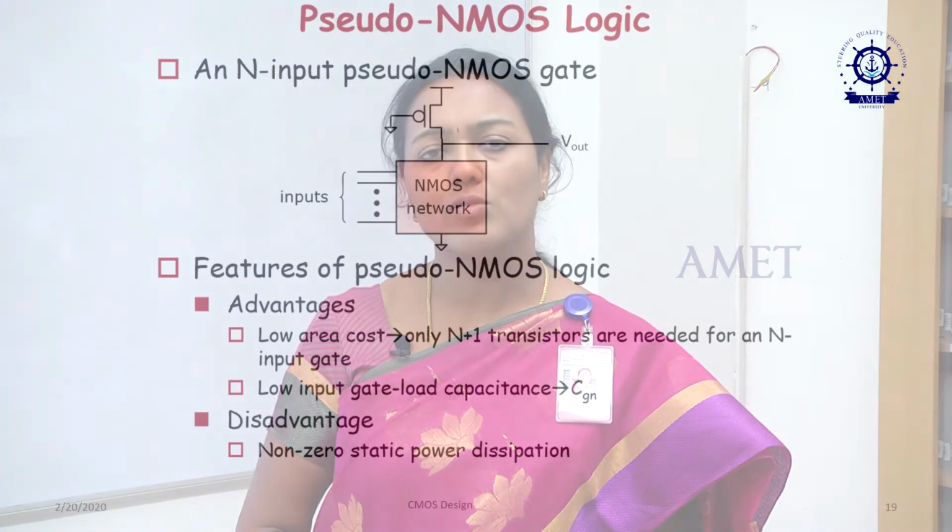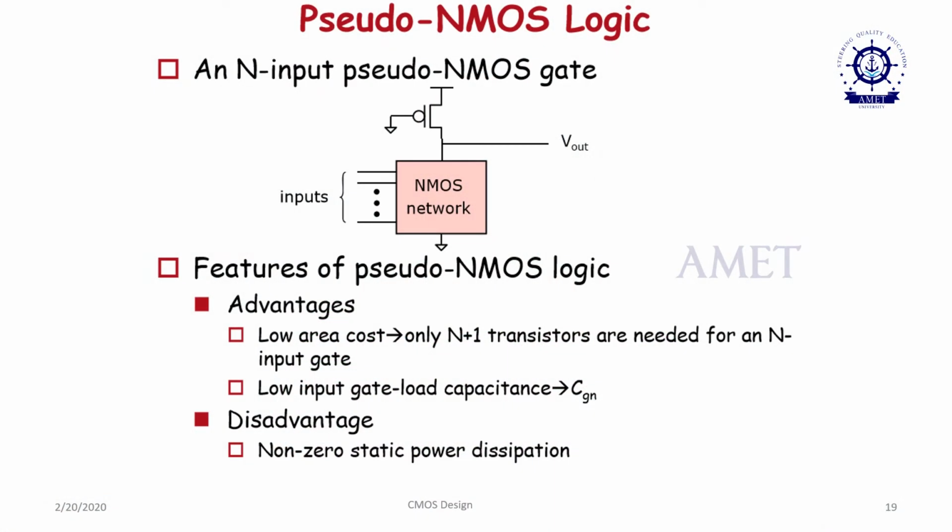Naturally, we are able to get the output. Similarly, for NOR gate, the 2 NMOS transistors have to be connected in parallel. We will get the output. So, we can verify the truth table of the NAND gate or AND gate, whatever it may be, based upon the input combinations which are applied to the lower part PDN.